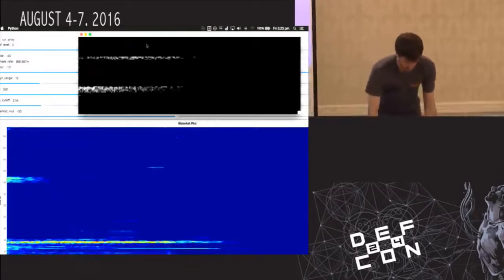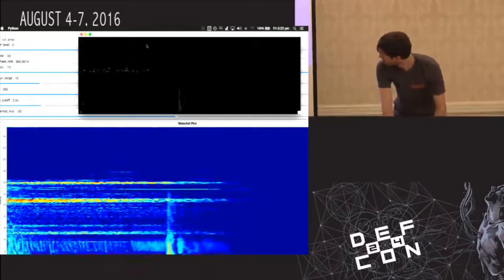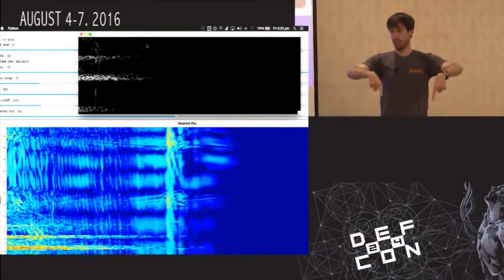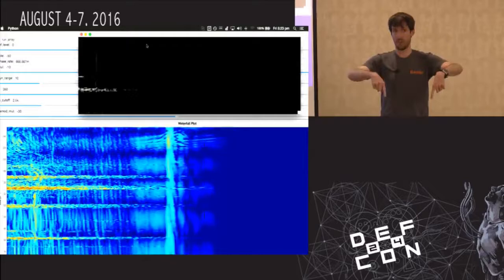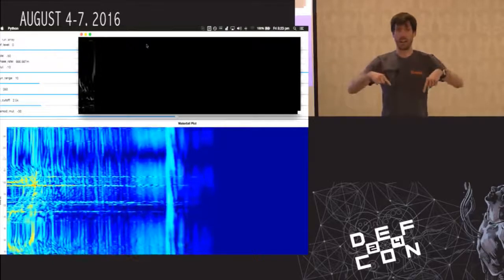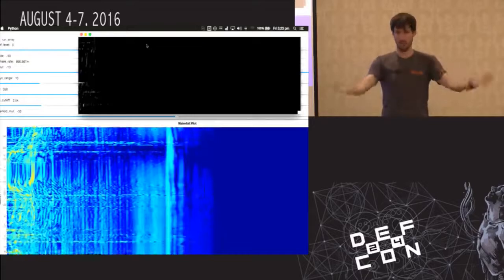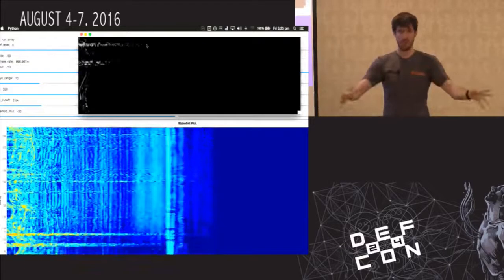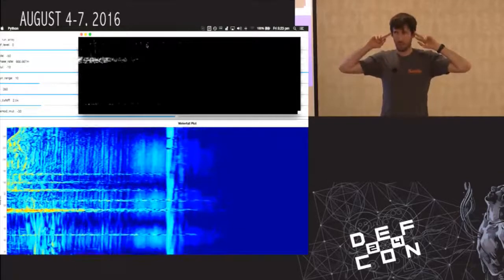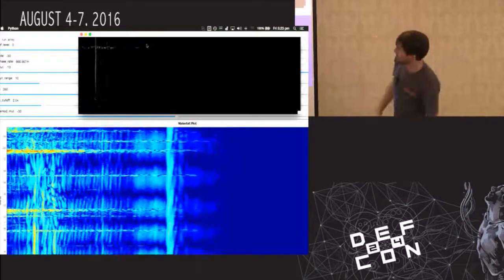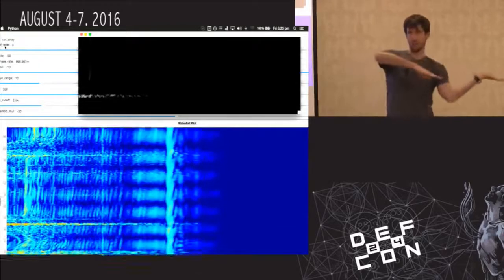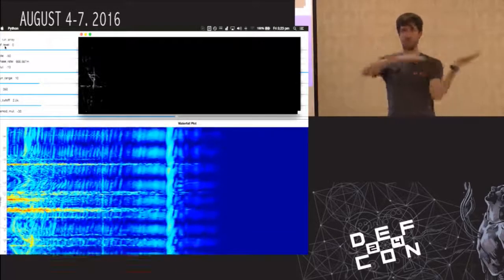But if you listen carefully, there are 2 speakers in this laptop, right? Which means we can create a phased array and try to get angle information out of the target space above the laptop. So what happens is if you listen, hopefully you'll be able to hear it, but it sounds pretty uniform right now. So what I'm going to do is click this button here, and then it's going to phase from the left channel through the right channel. So it's basically going to sweep.